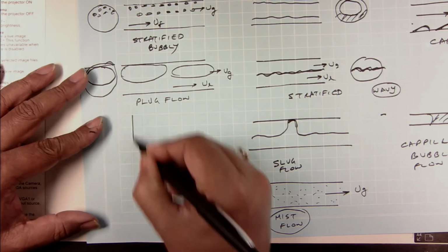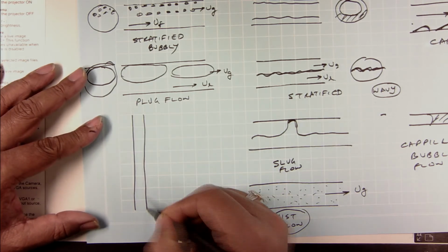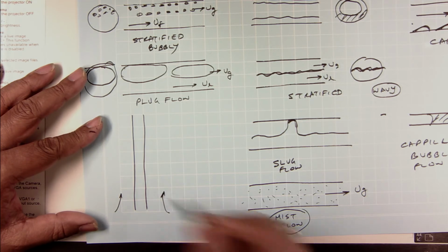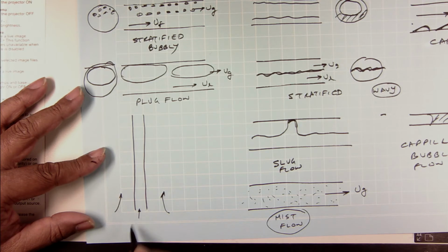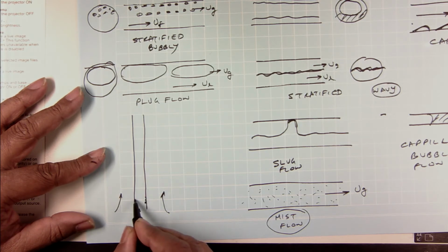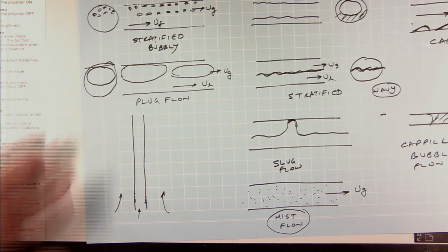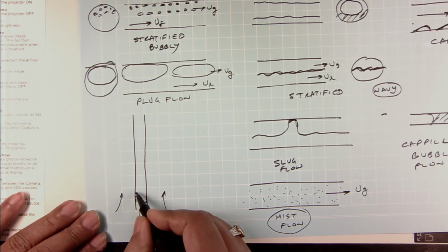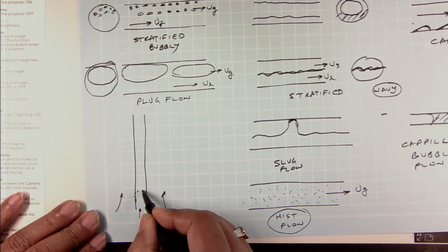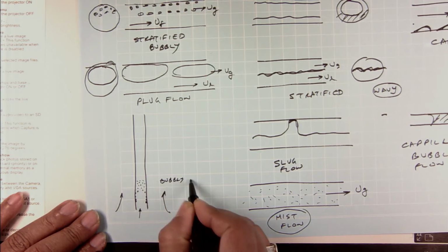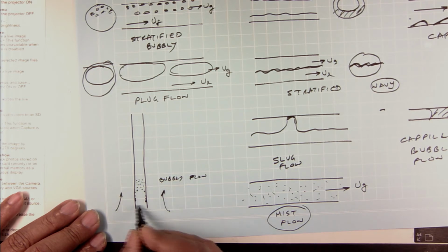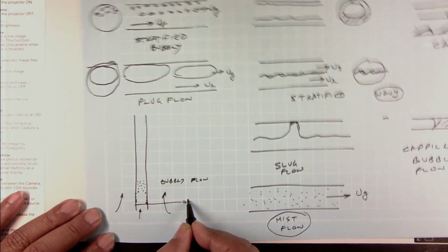So, I have a pipe that is in a boiler, I have hot gases flowing on the outside, and the liquid is coming in. Okay. So, at some point I will start nucleating vapor bubbles on the surface of this pipe, and these vapor bubbles are going to depart, and I am going to form a bubbly flow.